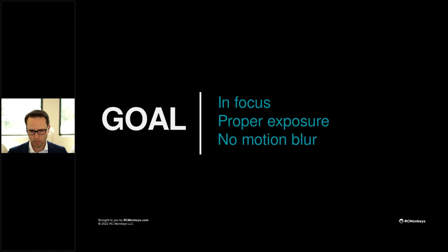And when it comes to motion blur, when we talk about the aerial equipment, the drones, there are some drones that have a mechanical shutter that prevents this motion blur, and there are some that don't. Like, for instance, the Mavic drones, they don't have a mechanical shutter. So you need to take that into account if you do any automated missions, and you need to adjust your shutter speed to make sure you avoid that motion blur. For the mirrorless cameras, those have a mechanical shutter, so you shouldn't have any issues there. And you're not running with the camera anyway.